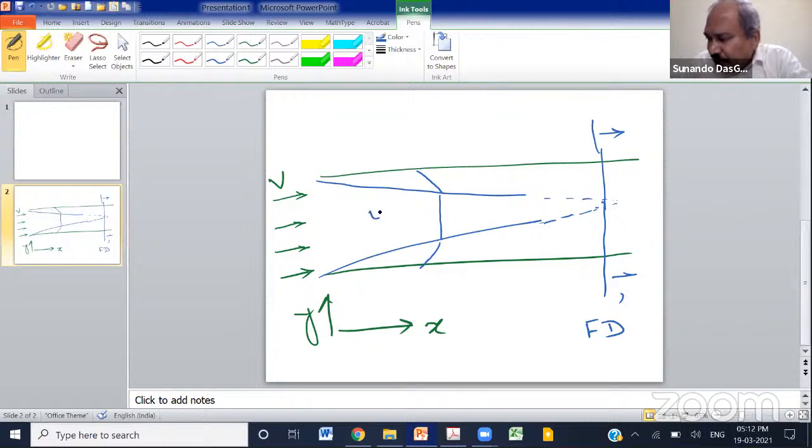So this is the U infinity, and you see that this U infinity is going to be a function of x. The variation in the pressure between point 1 and point 2, as I mentioned, can be obtained by Bernoulli's equation. In here, the gravity head would not change, but the area available for flow will keep on decreasing.